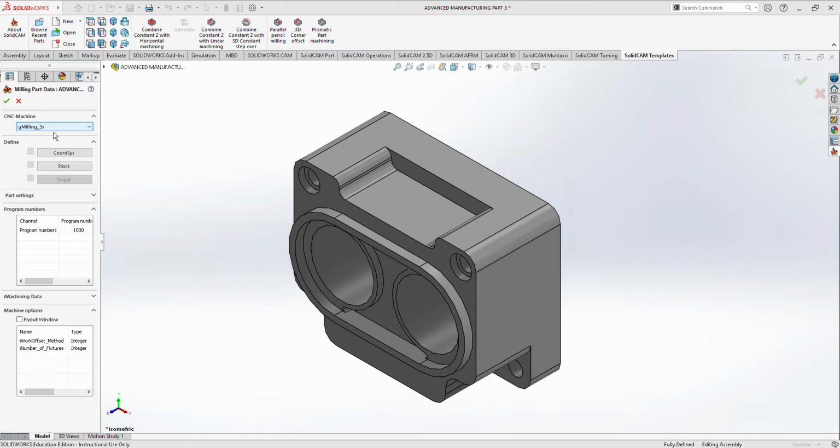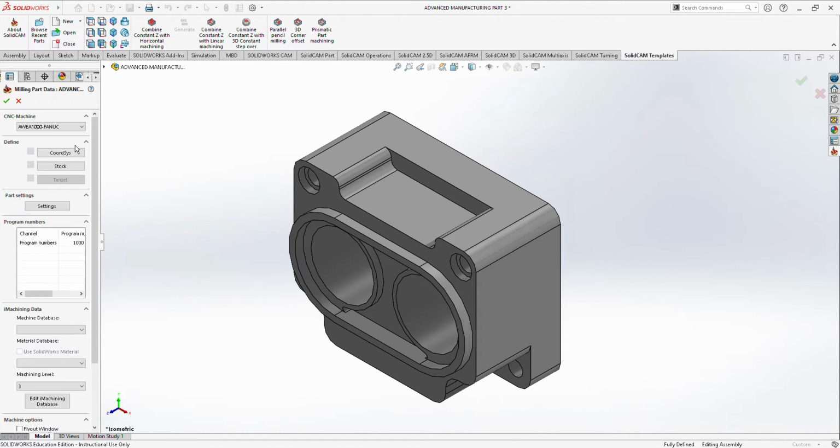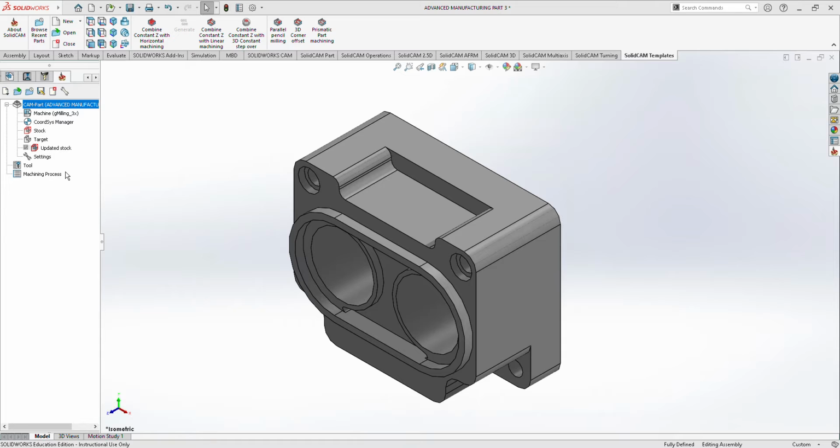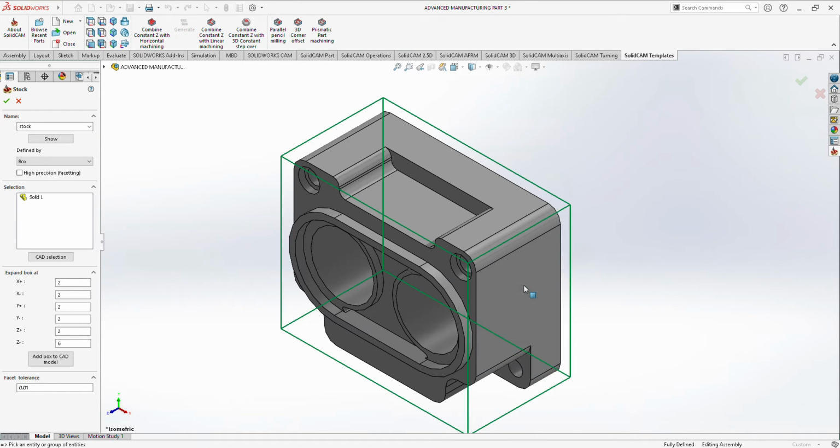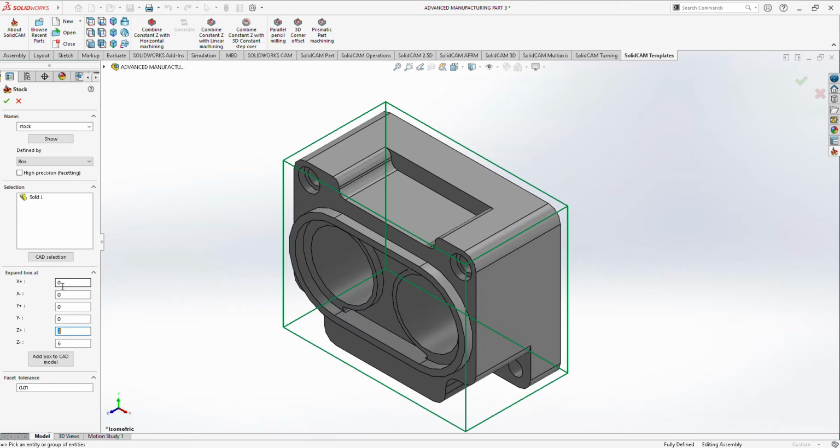Alright, so the first part is, as usual, you have to choose your CNC machine, and in this case I'm going to go with Fanuc as usual. Now you just have to set the dimension offset while cutting the tool. In this case I'm just going to put everything as 0 because I do not want any extra space between the tool and the body.